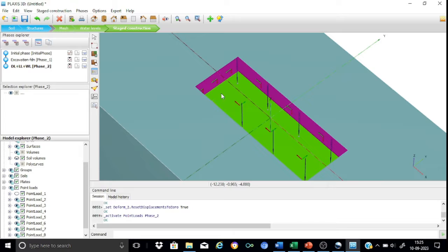You'll find that yes, this is the extreme column load. Just press it on, and now we know we need to apply the right load over here. We know that the corner load is 2500. It is a minus, that is, Fz. It is not a unit load. It is minus 2500 kilonewton. So that is okay. You'll find that here you can see the arrow has increased. So minus 2500 kilonewton is applied. Now let us proceed to point number 2.